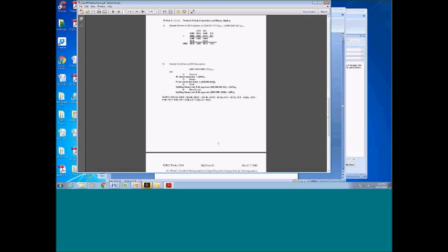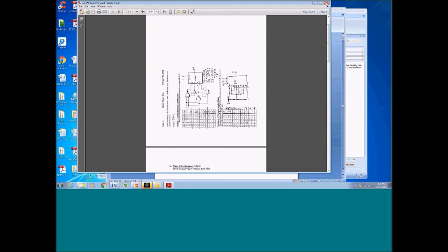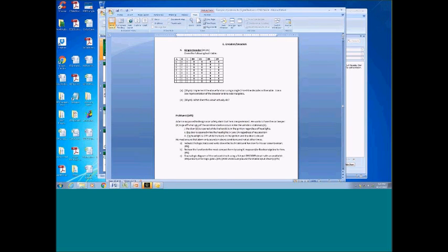These are other problems for an exam review. So again, here's a simple decoder problem. Basically, you're looking at some sort of output function. It's a little bit of an unusual thing, but how would you implement this with a 2 to 4 line decoder with enable? They just have to pick it out, and then I ask them, what does this thing actually do? In this particular case, if you look at it, it's only 1, 3, 5, and 7. So basically, it's only going to send out the odd lines.